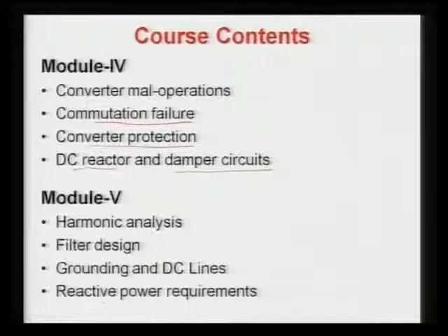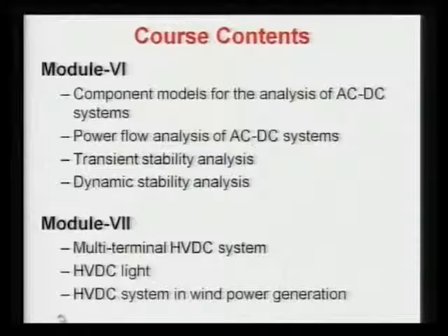Another aspect of this module is that it will also analyze the reactive power requirements. We will analyze even the filter circuit: it is designed to provide minimum impedance for particular harmonics, but this filter circuit also provides reactive power support to the converters for the fundamental components, and that will be analyzed, and we will see the requirement of reactive power. In module 6, which is completely dedicated to the power system analysis aspect,